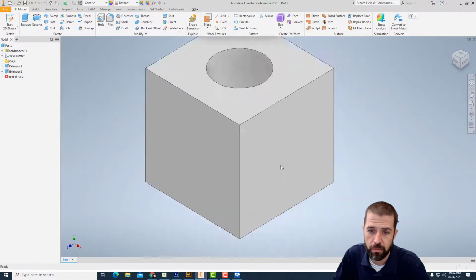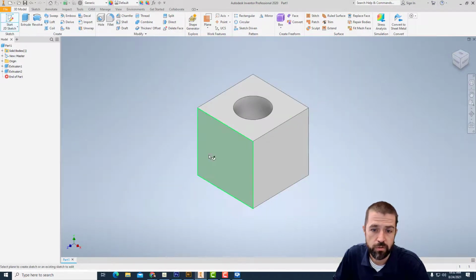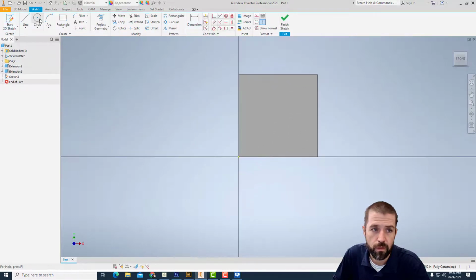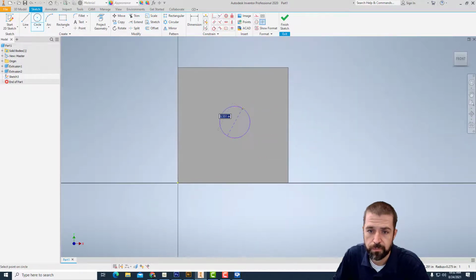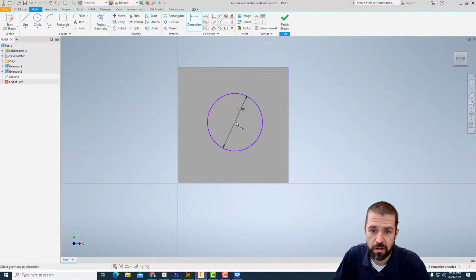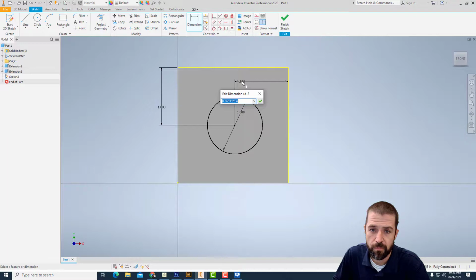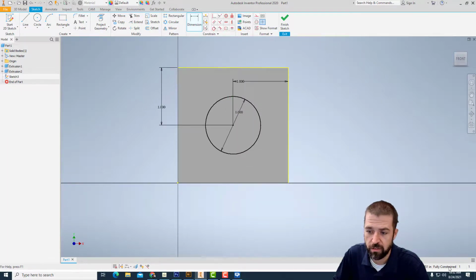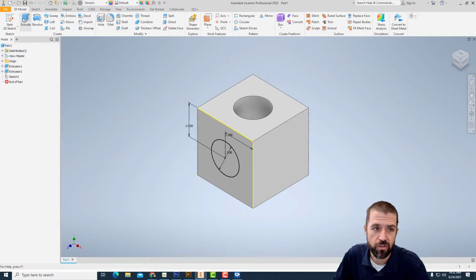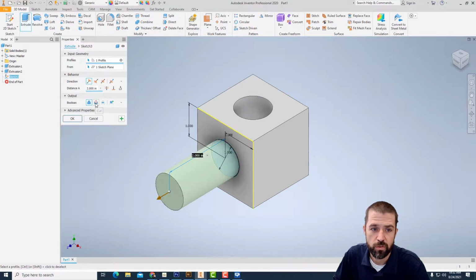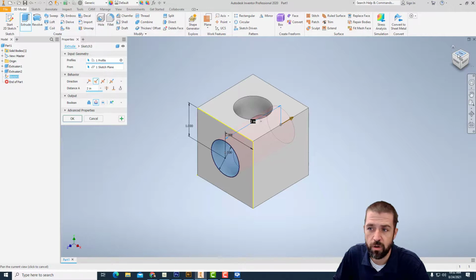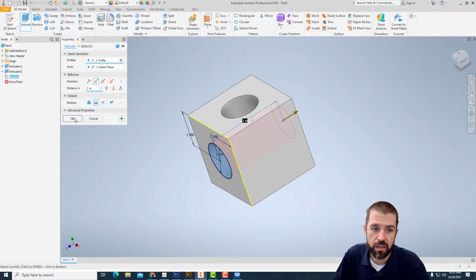I'm going to do it 2 more times. New sketch right here. Circle somewhere towards the middle. Type in 1. Dimension top to center. I'll go from the right side this time, right side to center. Again, down below here it says fully constrained. Hit finish sketch. Extrude. Switch it to cut, making sure that it's going all the way through my object. And hit OK.